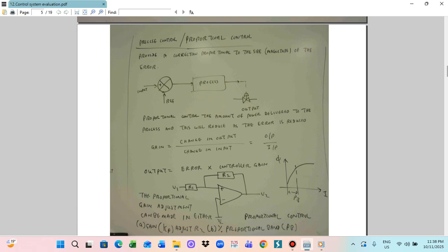When we are controlling the system, the basic control is the two position control, on and off, position 1 or position 2. For the water flow, when the water level is low, this is on, and then the water is flowing in. At level 4, off, and then the water stops. So this is the on-off control. This controller means it is open and closed between two levels, with upper and lower limits where the controller is working. So this is the level control and temperature gauge control. Those controls are utilized for systems that are not too precise.